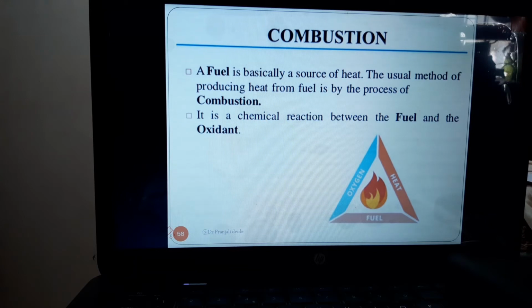Since the source of heat is the combustion of the fuel, a working unit must have whatever equipment is necessary to receive the fuel and air in proportion to each other and to the boiler steam demand, mix them, and perform any other special combustion duties such as distillation of volatiles from coal prior to ignition.